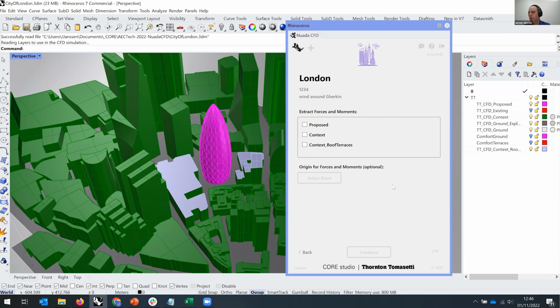So yeah, I think we do need that wind speed input in a way, so that basically you could look at, okay, I don't know, June 16th, 3 o'clock in the afternoon, my wind speed is 3 meters per second, and I could put that in. Or alternatively, if you do a structural loading, my design wind speed is 33 meters per second. Let's run it for that.